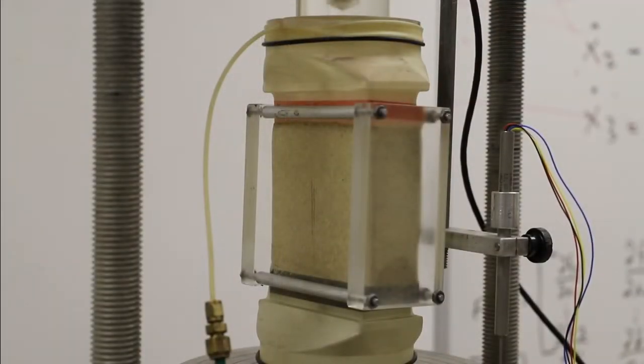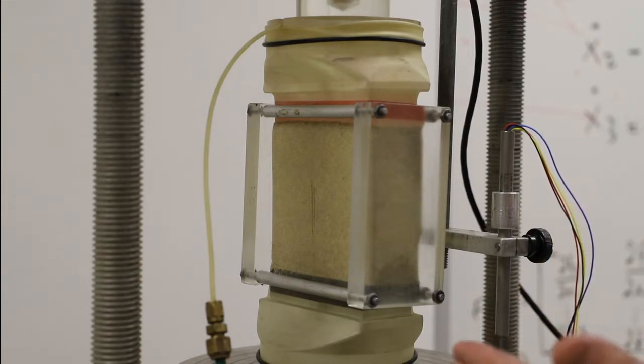So we're resuming with the dense plane strain test, and if we see a localized failure plane, we already have failure, right? And so we are just continuing to generate shear displacements, but they're all focused on one relatively narrow plane across the specimen.